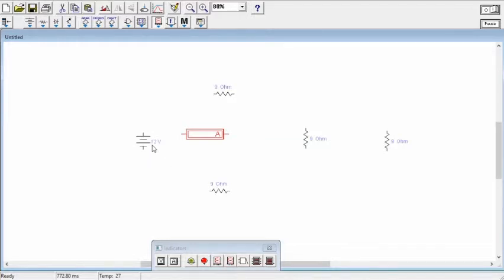So as you can see here, our source is negative, positive. The flow of current is from negative to positive, so we must consider the polarity of an ammeter. So here, since this is negative positive, the next one will be negative and then positive, so that the ammeter reading will be positive.